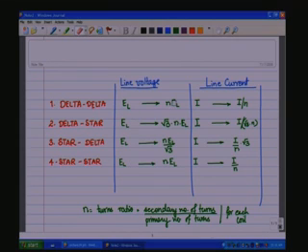So, in the case of the delta, for the same power and voltage ratings, this is supposed to have a higher core cross section area to withstand a higher voltage, but the gauge of the wire will be thinner, and in the case of the star it can withstand a lesser voltage, but the gauge of the wires will be thicker. Anyway, depending upon the application, the relationship between the voltage and the currents, one of the 4 types of configurations or topologies can be chosen.